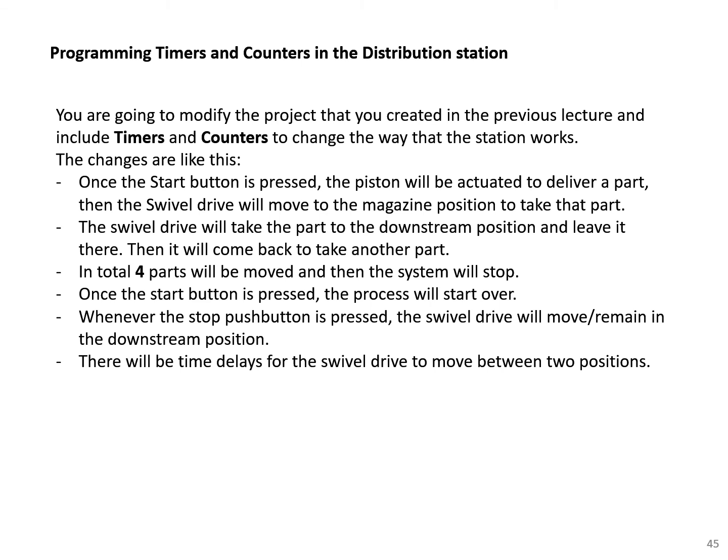So we need a counter for these 4 parts here. Once the start button is pressed, the process will start over. Whenever the stop push button is pressed, the swivel drive will remain in the downstream position. There will be time delays for the swivel drive to move between 2 positions. So here we have timers.